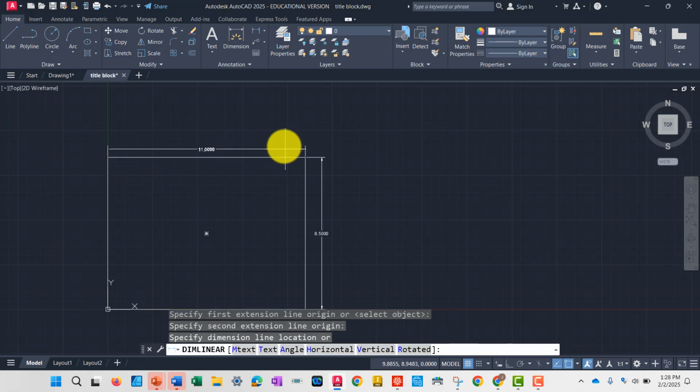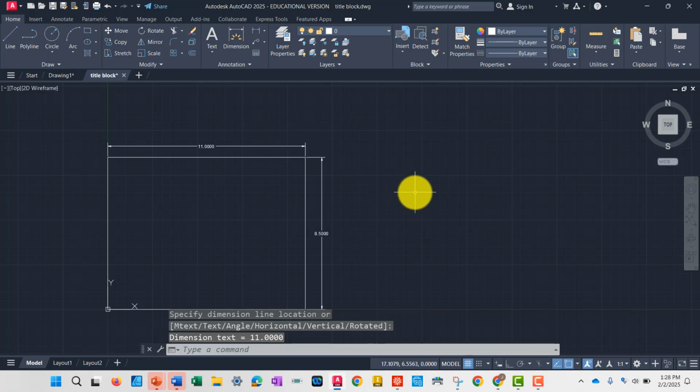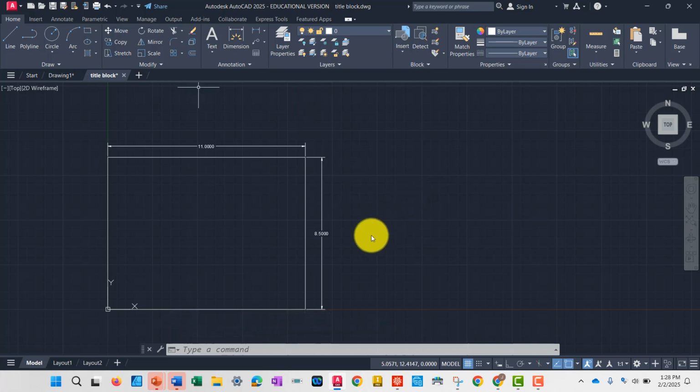Now, when you go to print something out, printers have like a little roller that it can't print to the very edge of a page. And so we're going to make another border that just shows the printable area. And I'm going to use 0.3 inches. It's usually a little bit larger than a quarter inch. And I'm going to create that second border with the offset command.